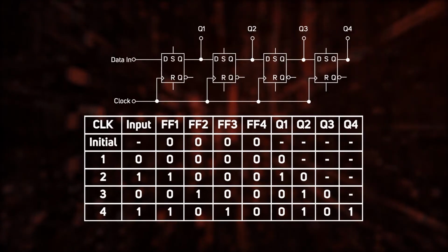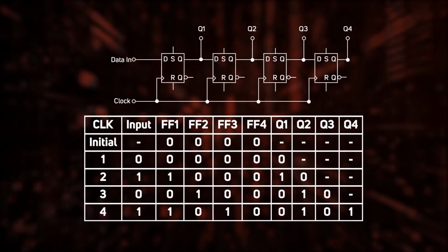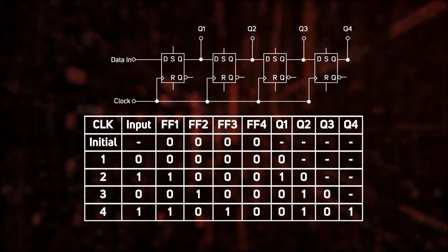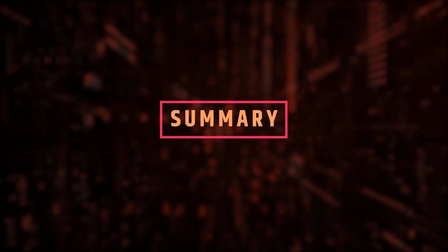When compared with the SISO register, which took around 8 clock pulses for loading and transferring the data, the SIPO register could accomplish the same task in 4 clock pulses. So, if we generalize, a SIPO register requires n clock pulses to load and shift an n-bit data in the register. The last point about the SIPO register: only right shift SIPO registers are commonly used in digital systems.